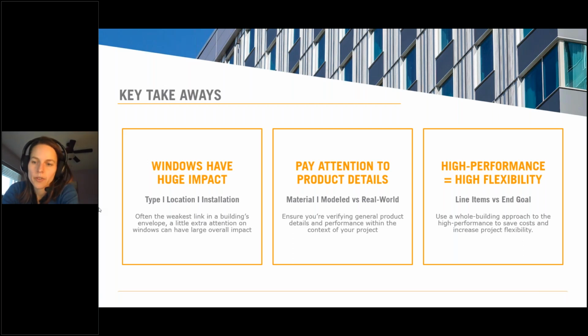Another good question here from Marilyn. What is the maximum size of a fixed window wall you can accommodate? So window wall, or the size of any window, is dictated by the design pressure. First of all, how much wind load is going to be on it, because any spanning members have to resist deflection. So that's a key one.